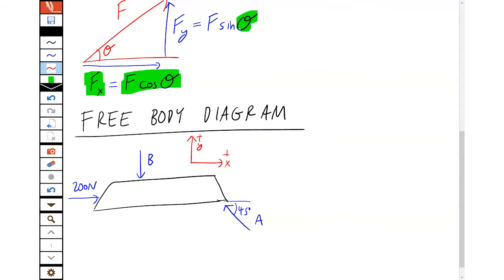So then we just do them. We can choose the X-axis or the Y-axis to look at. You might default to doing X first, and that always works well, but you can save a bit of time if you look at it and think, well, hang on, which has the fewest unknowns? Here we can see only one of the unknowns has an X component, whereas two of the unknowns have a Y component. So yeah, we do X first, but if you do that little check first, you'll sometimes find it saves you time. So I wanted to give it to you right here in this first lecture.